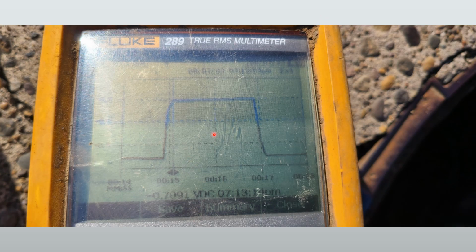And with the Fluke 289, you can then zoom in on each individual waveform. So this is that same measurement. We're just now zoomed in on one of those plateaus. So we have our larger negative value here, and then when we go off, we shift more in an electropositive. So this reading was negative 709 millivolts, or negative 0.709 volts. So for me, the interpretation where it becomes flat, that's our instant off value. That's where it's flat, CP current's been interrupted fully.